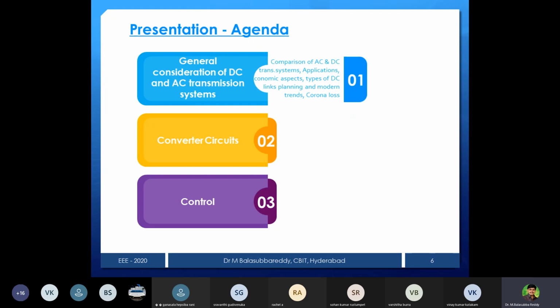There is a break-even distance, which they mention as, let us say, 500 kilometers to 800 kilometers. Beyond that, DC transmission is preferable when compared to AC transmission. Why did I mention the distance aspect? When you want to transmit AC power over long distances, that too bulk power, all these things are only an introduction; anyhow we will come back once again.